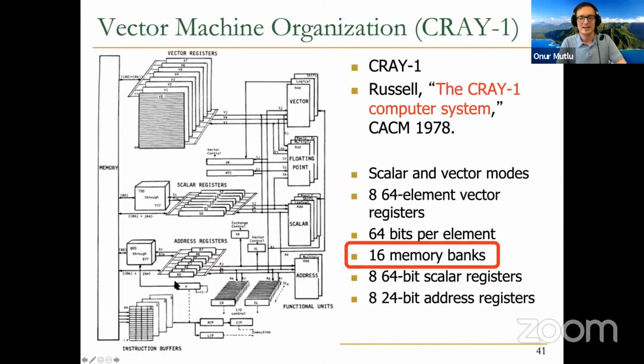Okay, so that brings us to memory banks, because memory is going to be very important. We should be able to fetch or load and store vectors from memory, and that's going to pose a bottleneck. So you may, for example, have 1 million vector elements. You can imagine potentially building 1 million adders to actually do the additions. But how you actually do the loading from memory becomes harder, because now do you really have 1 million different ports to memory? How do you actually start 1 million accesses?